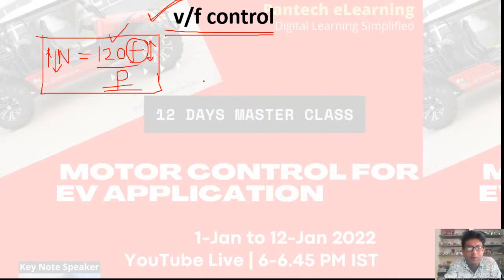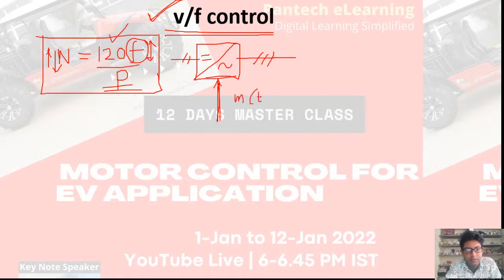But normally our power frequency is 50 hertz. So that voltage we can vary, but the frequency is normally fixed, it is not possible to vary. If I make one inverter which is taking DC voltage and converting it to AC voltage, and here if I use the PWM, we will learn it in some detail today. So if the frequency of the modulating signal of the PWM is changed, then the power frequency output of the inverter also will be changed. So in this way I can change the frequency, which will in turn change the RPM of the machine.